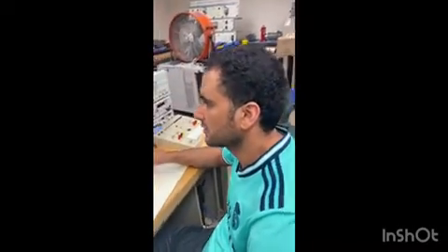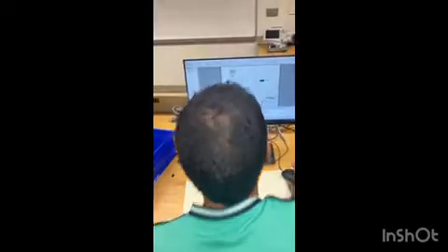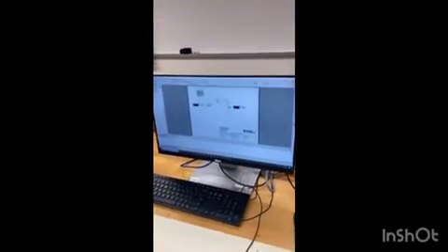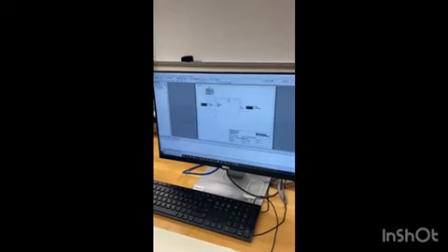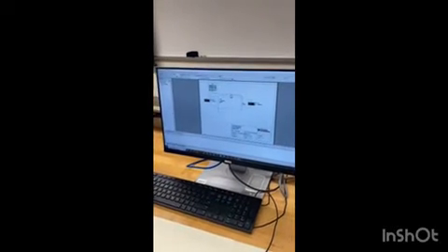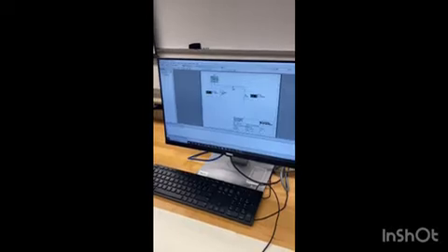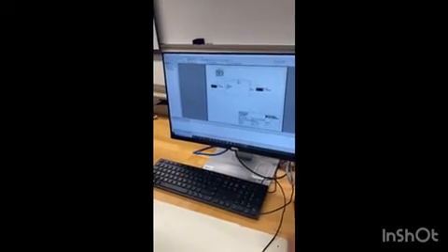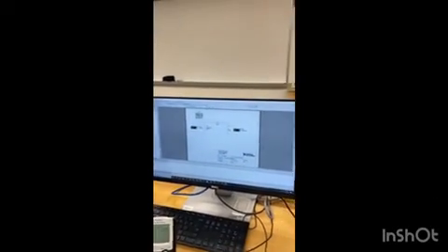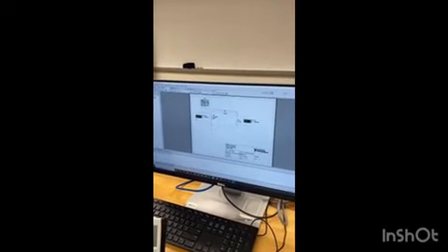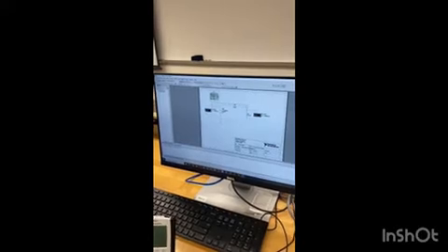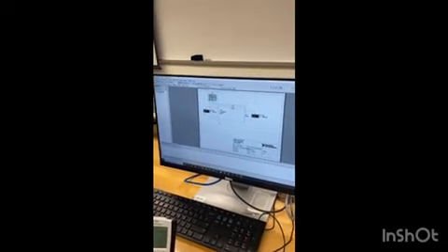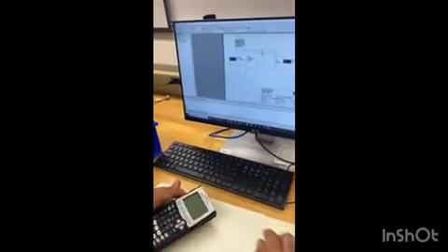Hi, my name is Mustafa. Today using Multisim, I'm going to show you how we can measure peak to peak and frequency and period. Gonna run the circuit. We choose 7 volts V peak to peak divided by 2. Gonna give us 3.5 V peak multiplied by 0.707. Gonna give us 2.474 VRMS.